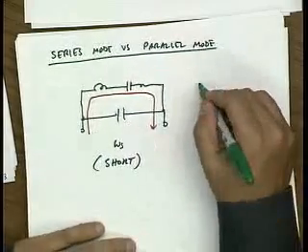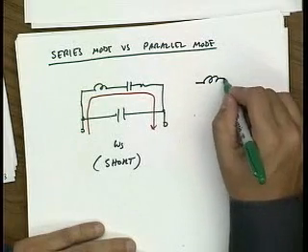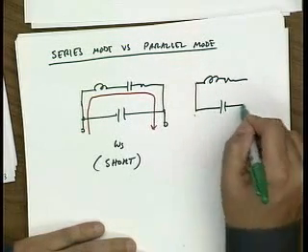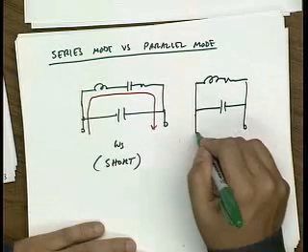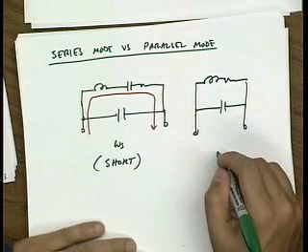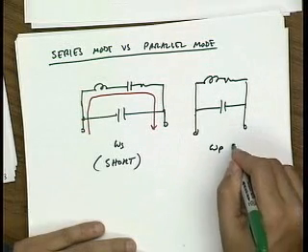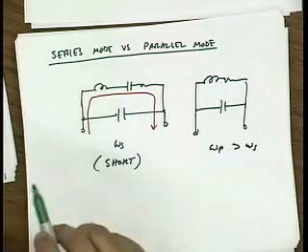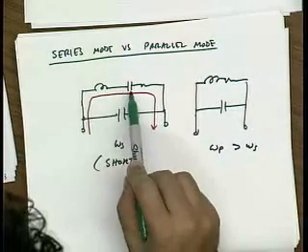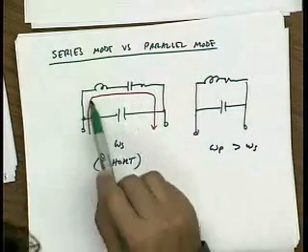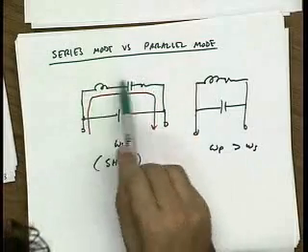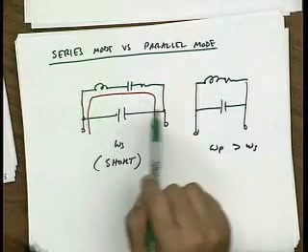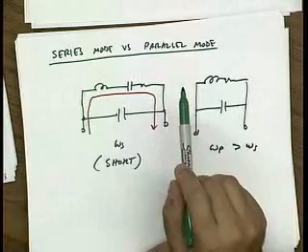On the other hand, the parallel resonant mode is basically a frequency above omega s. If I go above omega s, that means this branch starts to look inductive, so I have an inductor in parallel with a capacitor, and it will also resonate at some mode.